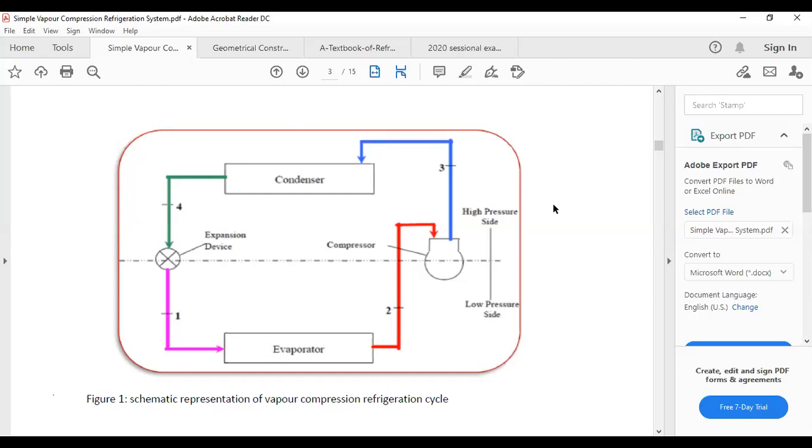So never should you decorate even the condenser. If you go to some homes, they have put tablecloths on the fridge and the condenser and whatever. No, no. That place behind there has to be left uncovered, because it's the place where the fridge is releasing that heat from the system.